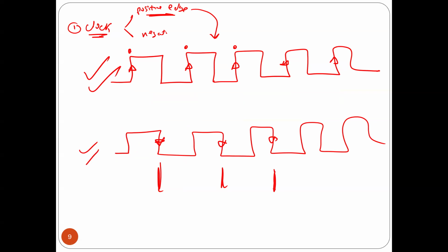Okay? But again, let me make it simple. Look here, guys. Usually for any digital system, we use a clock. You need to understand the concept of a clock. The concept of a clock is just a square wave. This clock is connected to all the circuits in the system. All the circuits are using the same clock, and it is used for synchronization. Synchronization means we want to do something at specific times. All of us. I want to avoid that one circuit is going to produce some value faster than the other one. No, all of us are synchronous. So that means even if the input changes here, you will only see the output at these specific times.